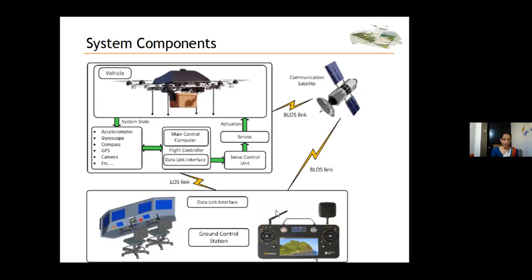The flight controller can have multiple sensors integrated on board or communicate with an external sensor unit. So you can see here some of the UAV system sensors included with this system. Why do you need these additional sensors? For example, if you want to do navigation and advanced measures, you need some additional sensors like this. For example, you need a GPS interface to the flight controller, and you need a compass interface to the flight controller.